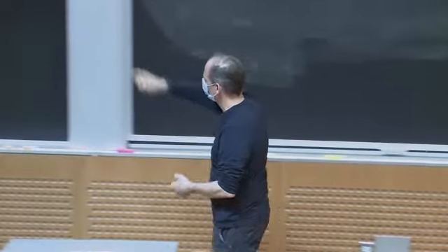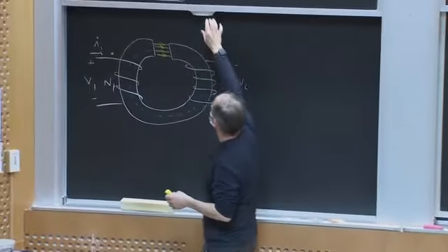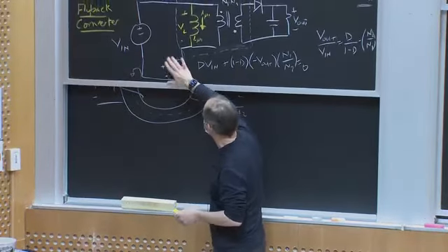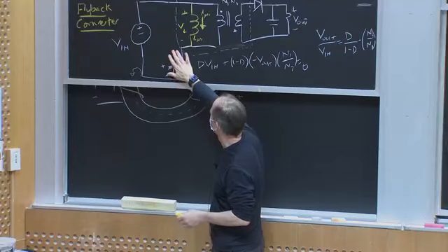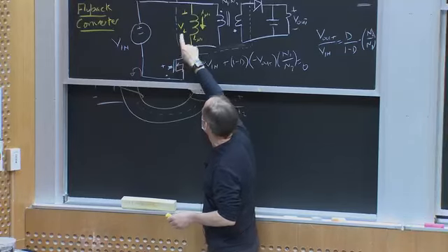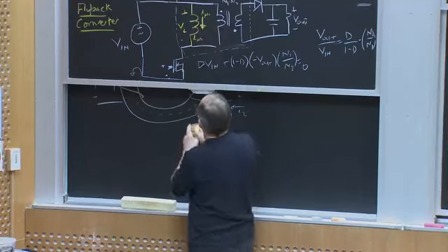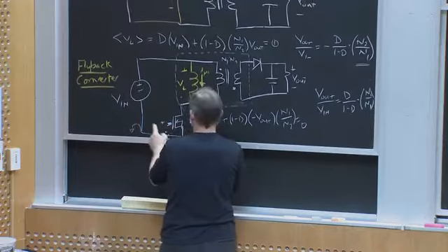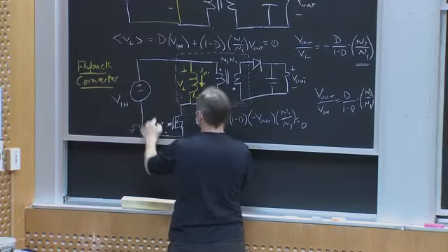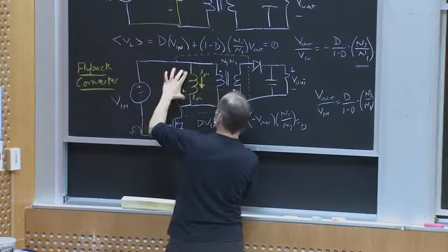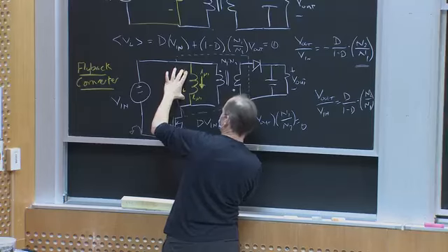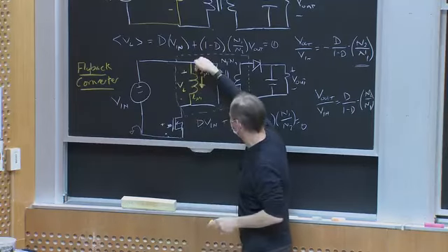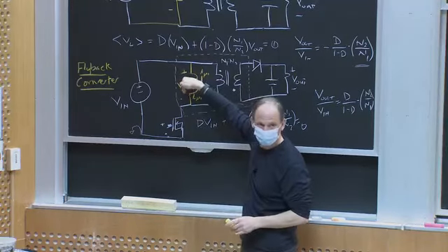So what are we going to do? In the first part of the cycle in this converter, I turn on this switch. This magnetizing current basically circulates this way, and I'm applying Vn across the magnetizing inductance, and the current I mu1 is linearly increasing, right?